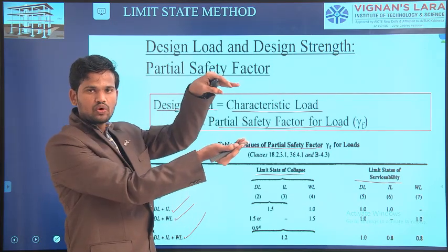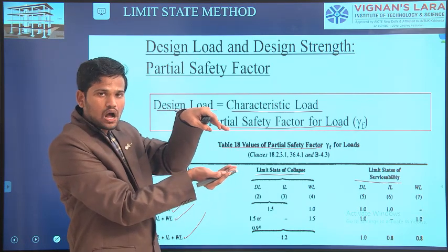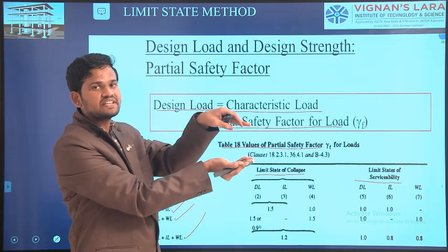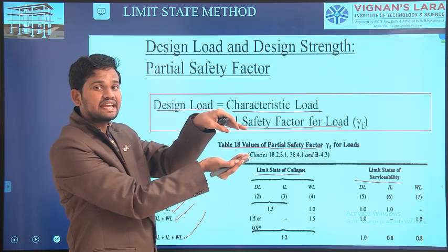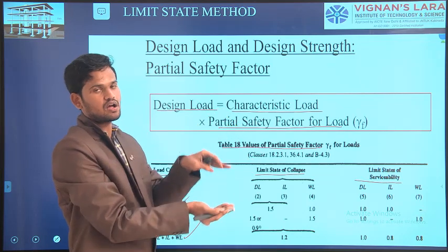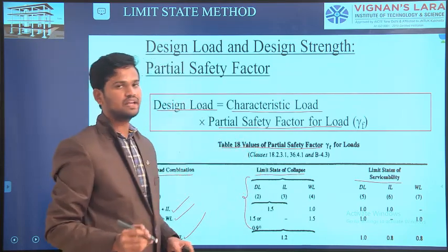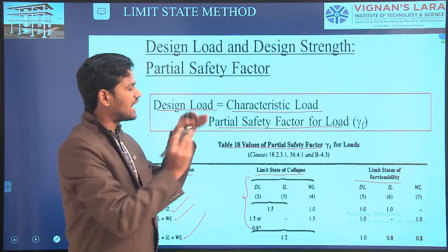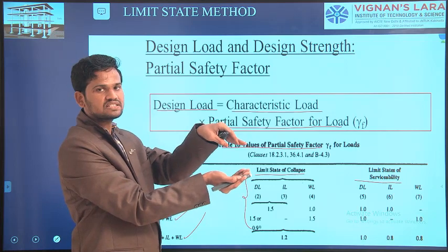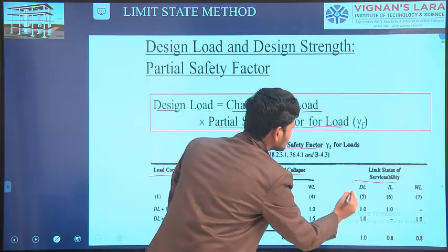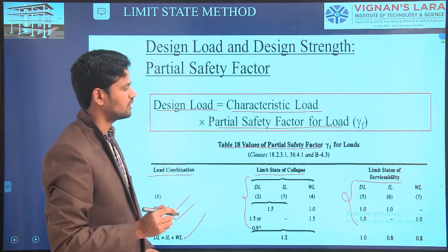That means you are designing some structural element. For designing this structural element, what parameters are you considering to design the structural members? If you want to design the member so that it does not fail in flexure, compression, shear or torsion, we have to take these loading conditions and these factors of safety. Otherwise, if you want to design the structure without vibrations, cracks or deflections, we have to design the loads by using these values: limit state of serviceability, limit state of collapse.